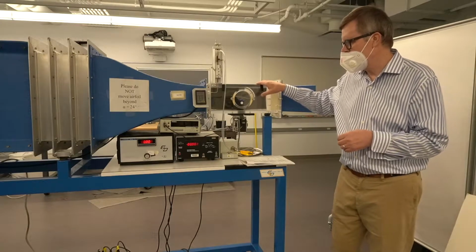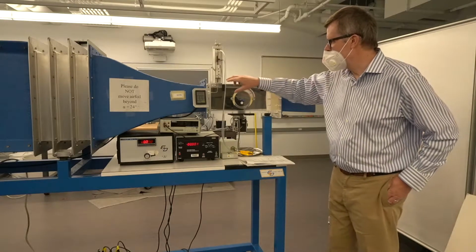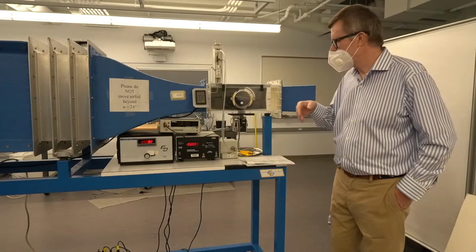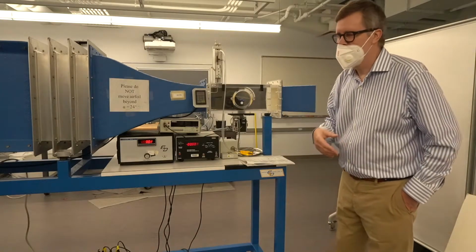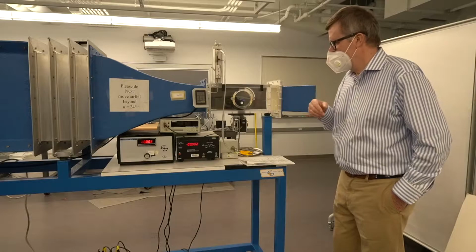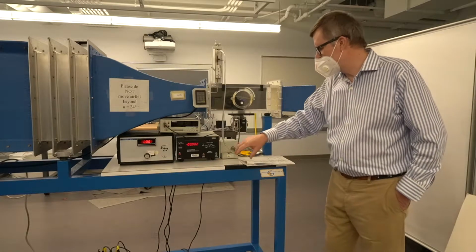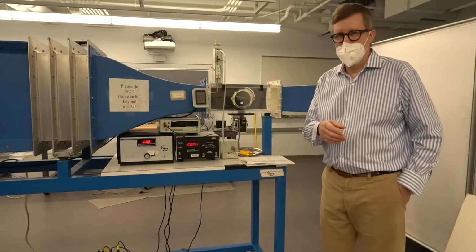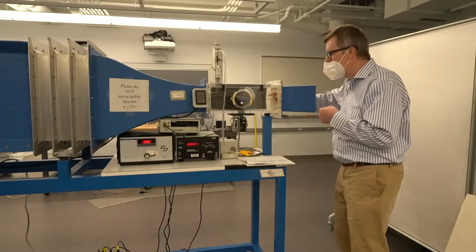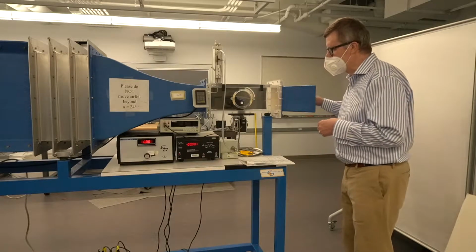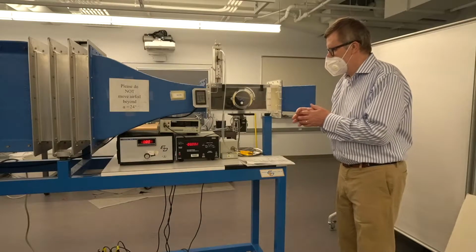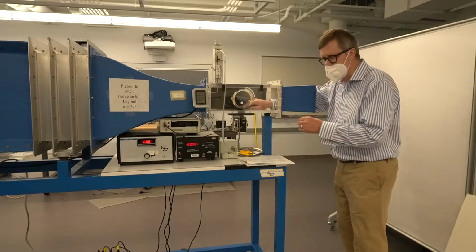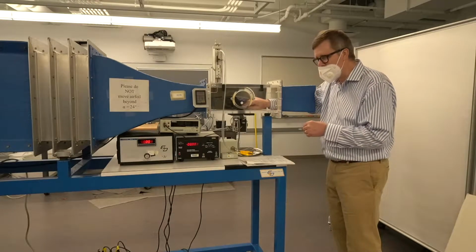So this wind tunnel has a pitot-static tube up here, so you can measure the velocity of the flow using that, using Bernoulli's equation and the pitot-static tube. And so we measure the pressure using this transducer here, and to get our force on the body, just the airfoil in here, to get the force of the fluid on the airfoil, we've got the airfoil suspended by a sting, which is a long kind of rod that's underneath this black thing here.